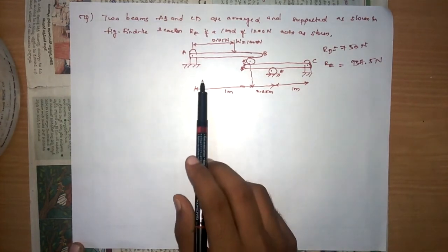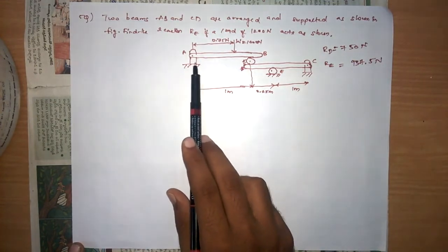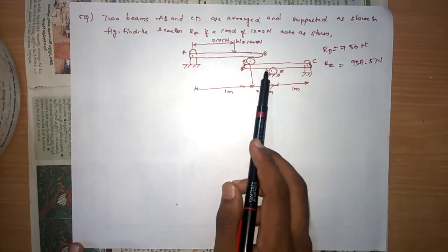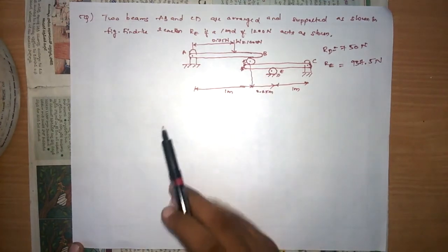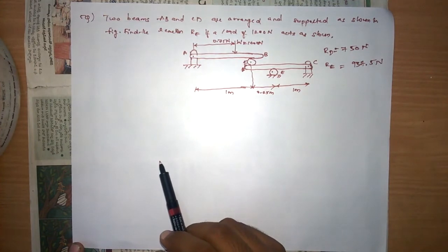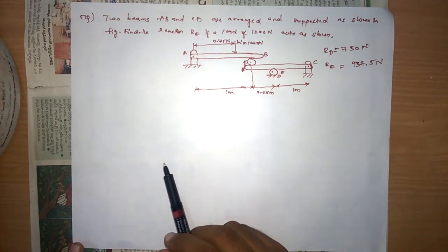However, this can also be solved by the same method. Separate these two beams, show whatever reactions are acting on them, draw the virtual diagram, show the virtual displacement, then the algebraic sum must be 0. From the principle of virtual work, we can get the reactions.